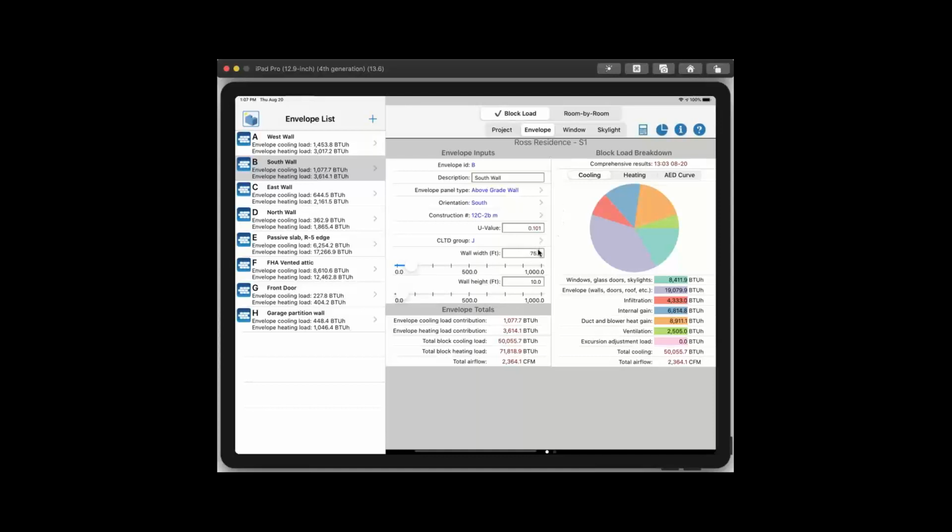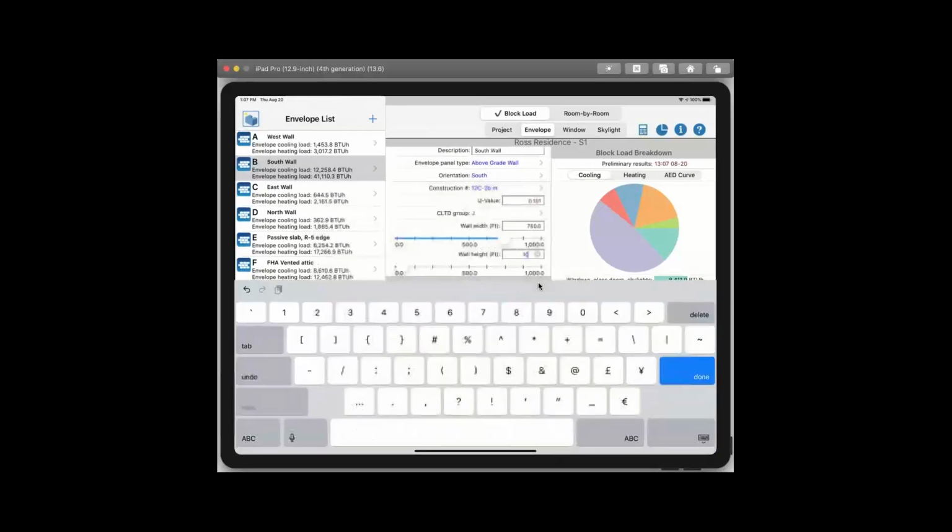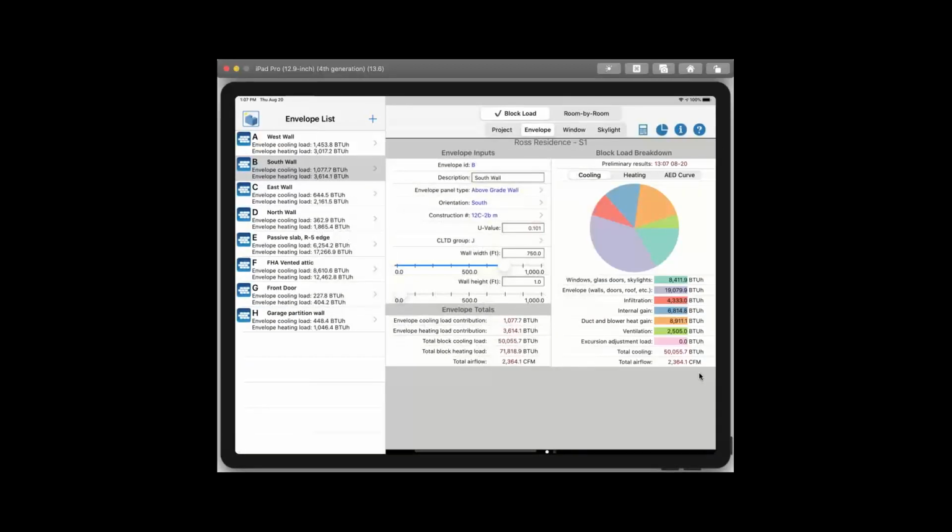Well, all you need to really do is, in this case, enter 750 here, and enter 1 here, and it's the same thing. So in essence, you're entering the area here, and you're entering 1 here. I understand that, but it's very non-physical, because really what the program's looking for is an area, right? Exactly. It doesn't care anything about the length and the width.